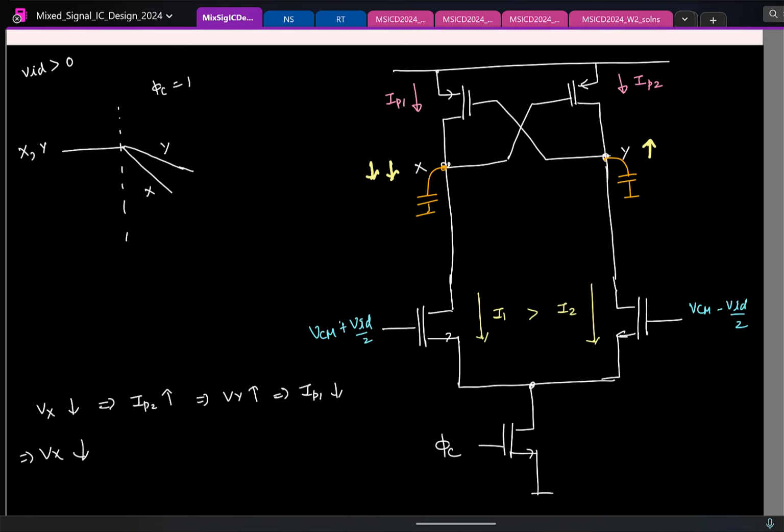So let us say Vy will start to increase and reach VDD, and Vx will reduce and go to 0. Okay. And here is where you get the e power plus t by tau behavior, exponentially rising.